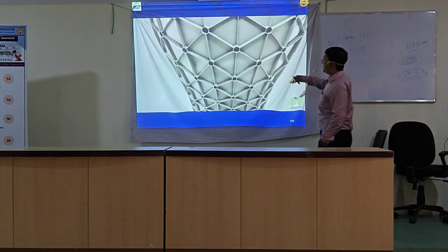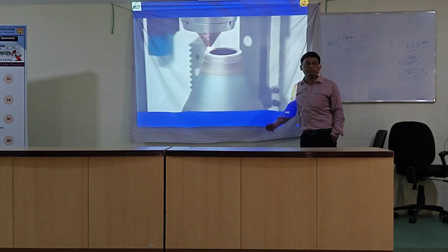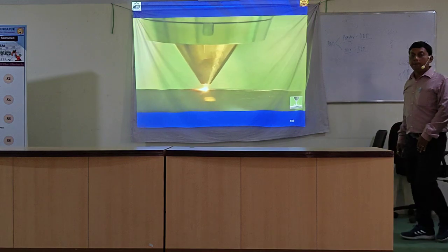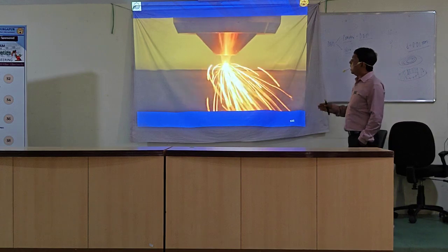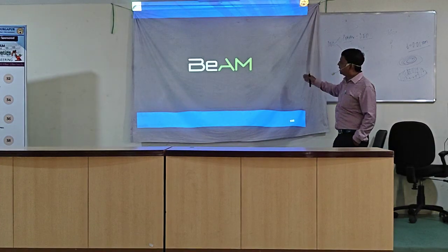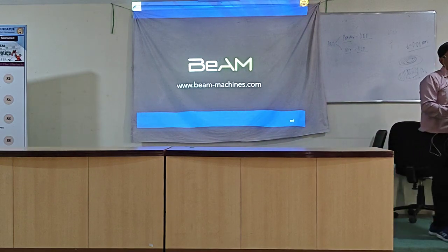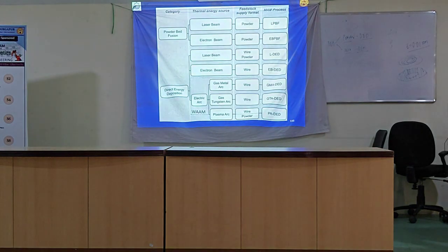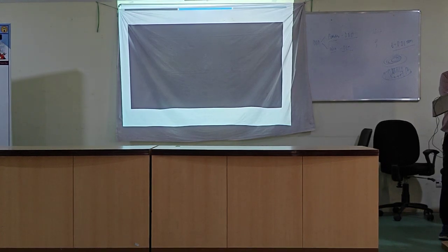If a certain portion of the gear tooth has been worn, you can deposit the material using this process. That is not possible in the case of PBF, powder bed fusion. Powder bed fusion that we just discussed is only an additive manufacturing process. But powder DED is both an additive manufacturing process as well as a repairing or dynamically repairing methodology. So let us see this one.